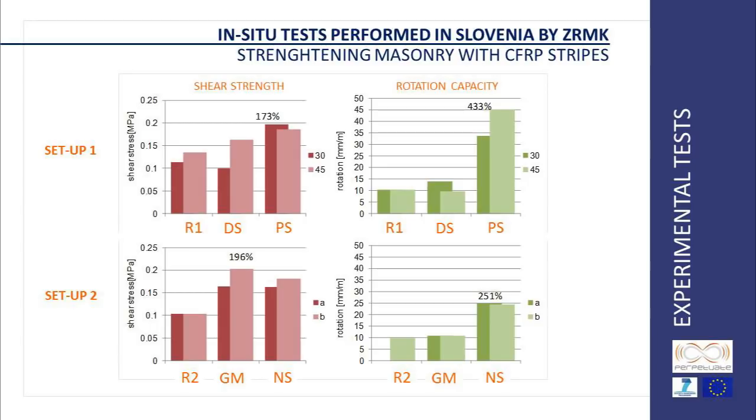The results are very clear by aggregating the shear strength and the maximum rotation capacity obtained. All the tested strengthening techniques provide an increase in the strength of the wall, but the more remarkable differences are in the ductility. Perpendicular thick stripes resulted to be the most efficient.